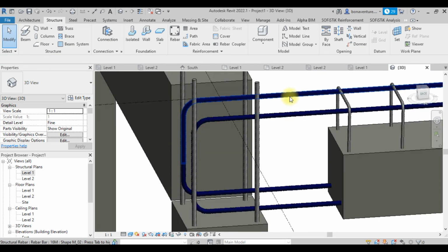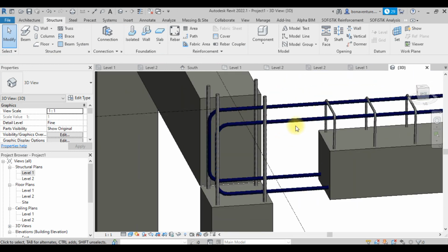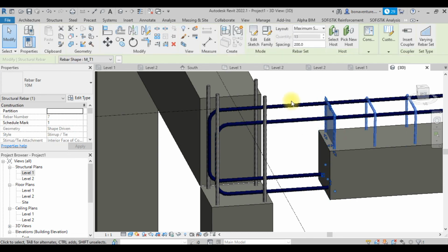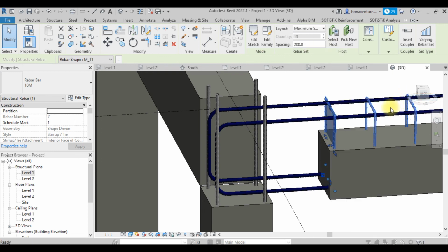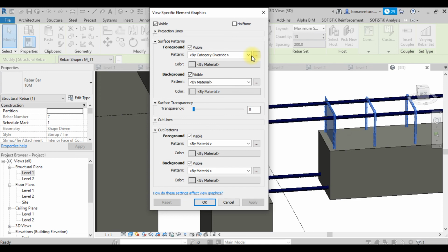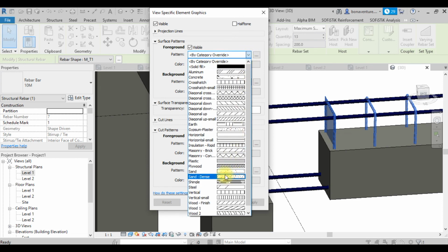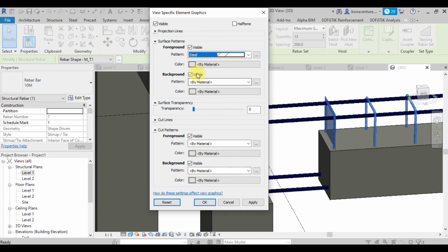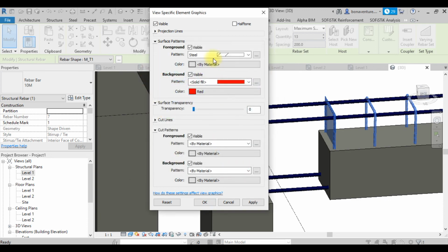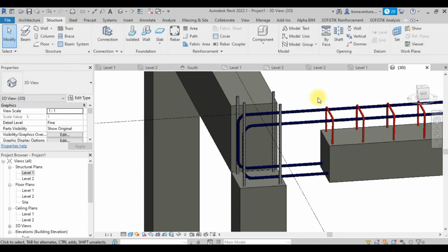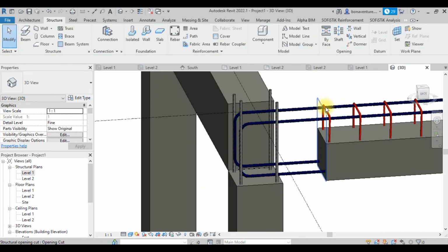But it's still preventing it. You can still see it as if it says Rebar. So coming under this particular, you now need to go to this element, in this case element. So do the same thing. Choose the steel. Now come back to material. If you come down to this place, you now need to choose the color. Maybe I choose red. Okay, good. Apply. So this is basically how you can always change this.